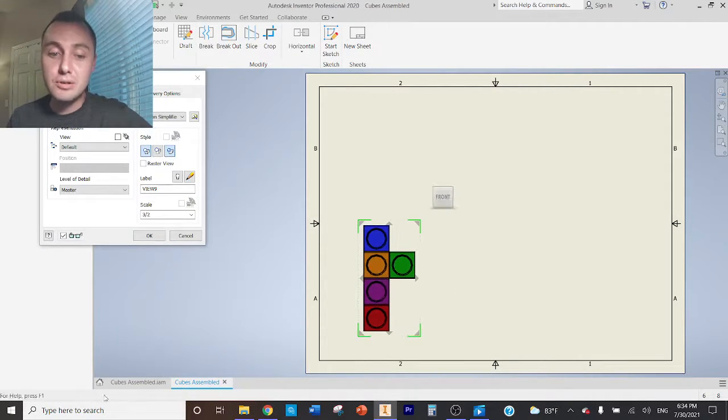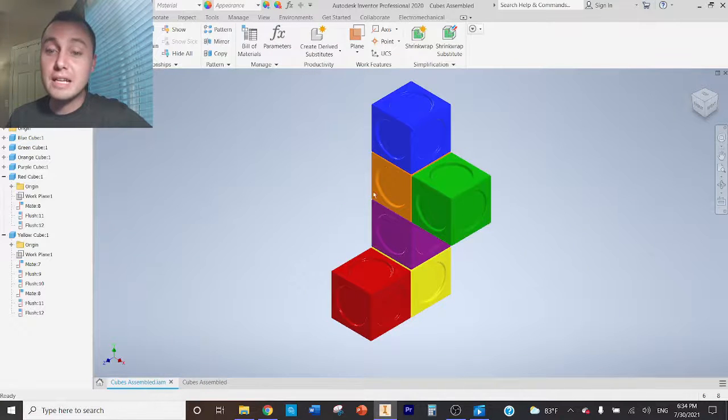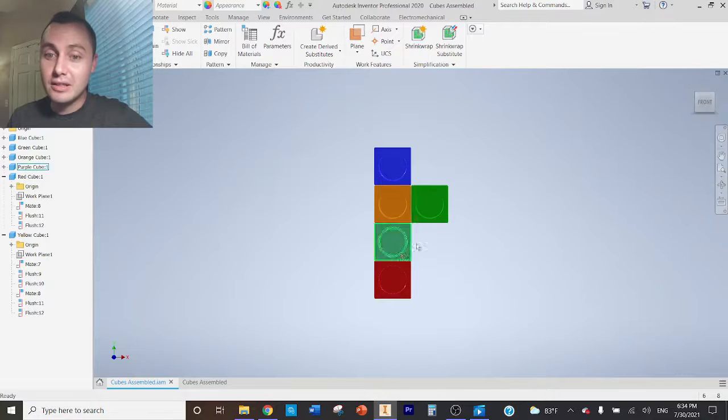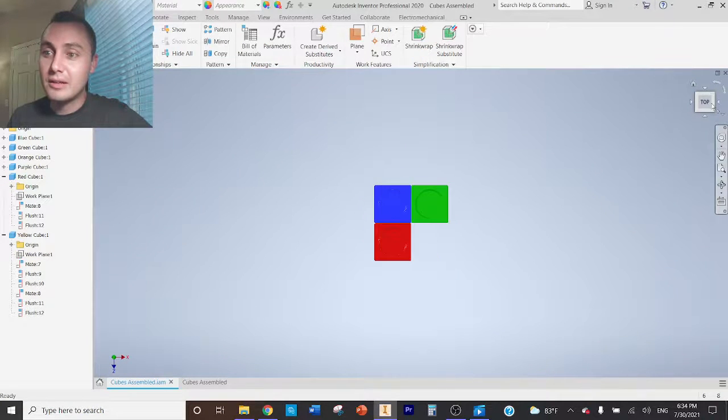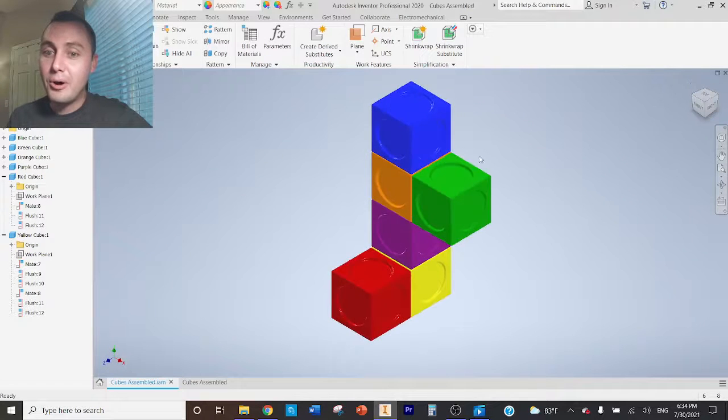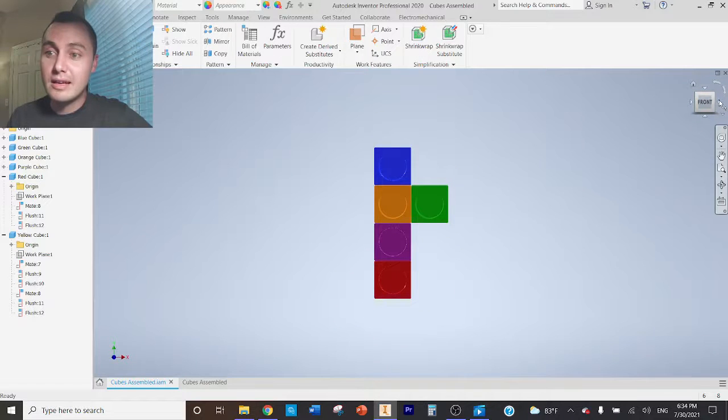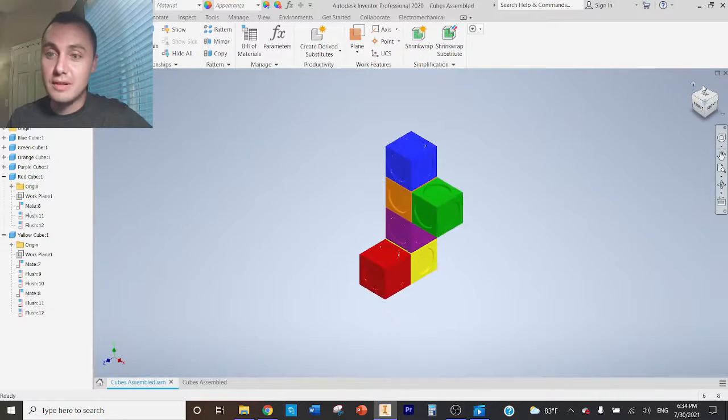Using that same cube, I modeled the same one he used in the video. You can see this cube over here where my mouse is on the right side of your screen; that is our orientation box. You can think of this as a glass cube. If I click here, I can look at this from its front view. If I click on this side, I can see it from the right view, and then from the top, and so on. I can orient this however I like. The home view gives us the 3D view, while all of these other orthographic views give us only the two-dimensional version of that object.